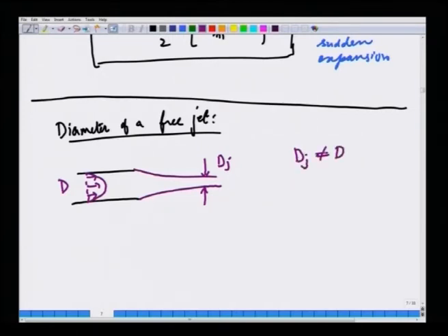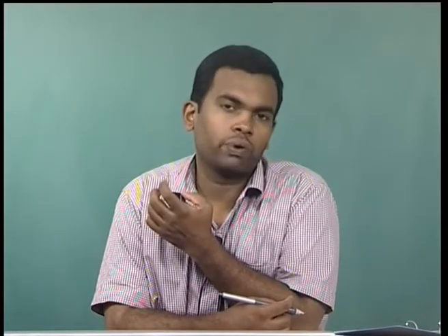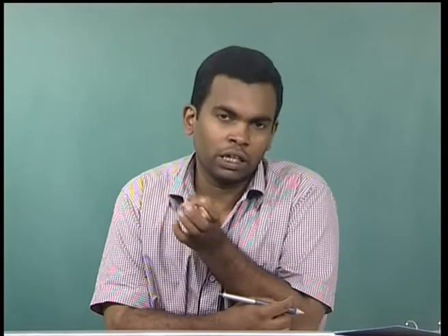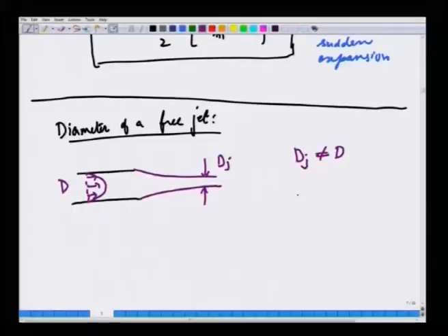Okay. This is simply because of the lack of resistance to flow when the fluid exits into the atmosphere. So, what happens is it generally thins a little bit. The reason for that is that at constant flow rate, the volume that flows inside and outside is the same. So, we have V times d is V jet times d jet. This is from mass conservation.